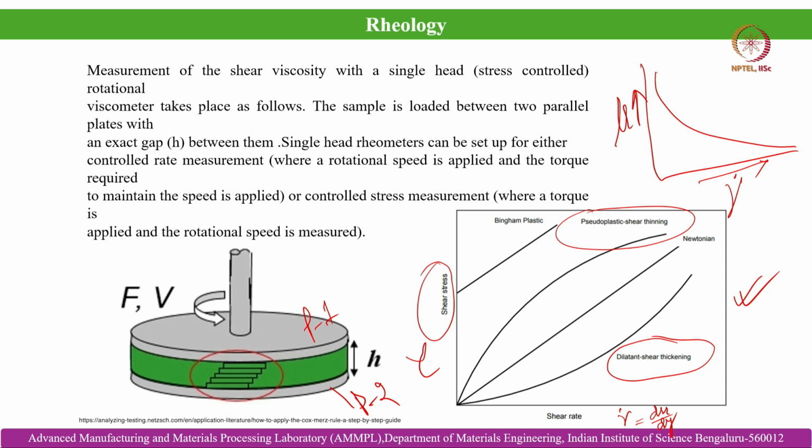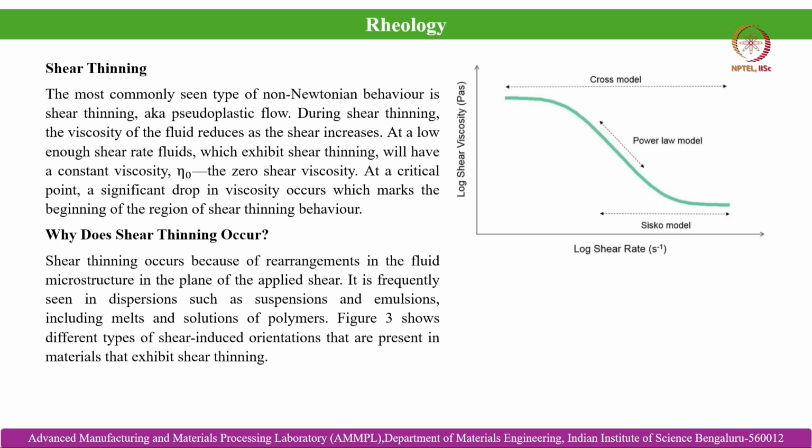However, because the fluid is in motion and there is a shear rate generated by the shear flow, and because of the shear thinning nature of the solidifying liquid melt, the viscosity drops, and that is why it remains flowable enough and is capable of filling the complex contoured component cavity, and thereby we can get sound structural parts. So here the shear thinning behavior is explained properly.